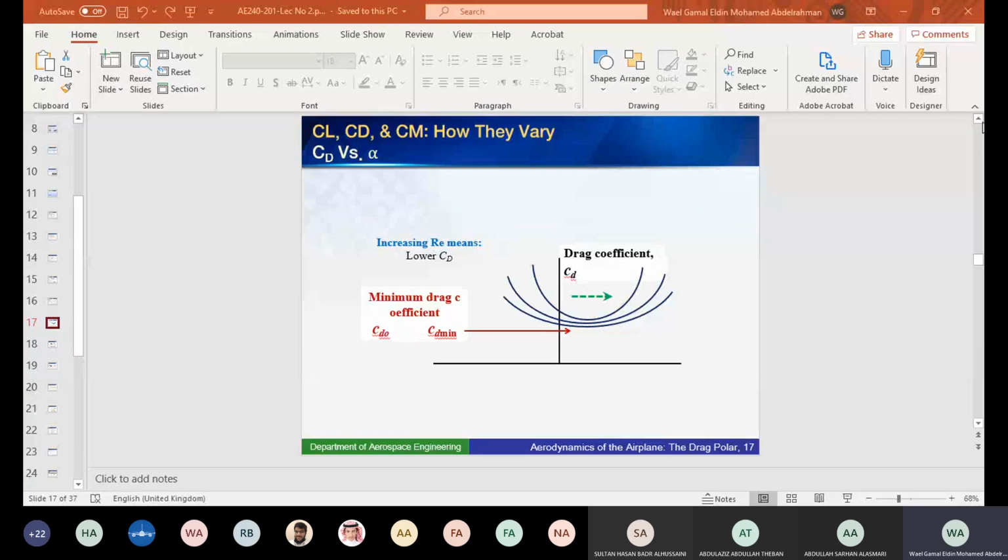The center of pressure is the point at which the resultant aerodynamic force acts, whether it's a lift or a drag, all of them, the resultant R acts at the center of pressure. You have a pressure distribution around the wing. It has a resultant. It acts at the center of pressure. So mixing your definitions together works fine. I hope Yusuf will tell us about the aerodynamic center. That's the second one that we have.